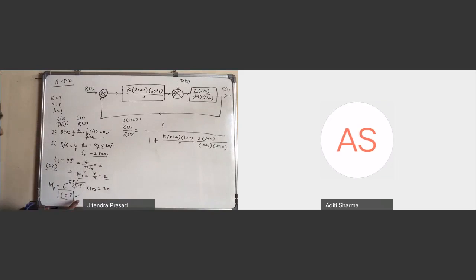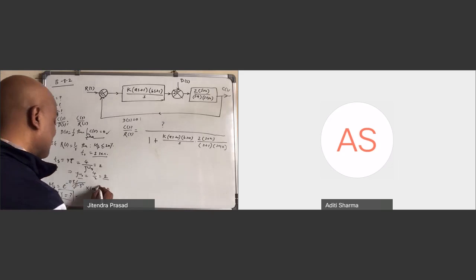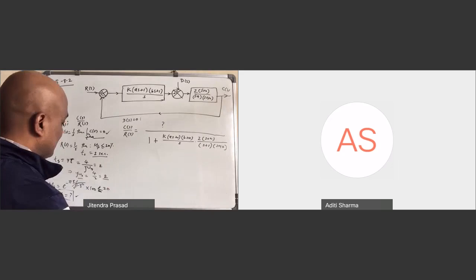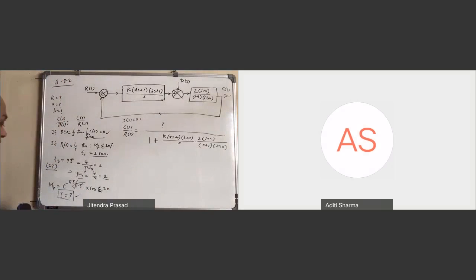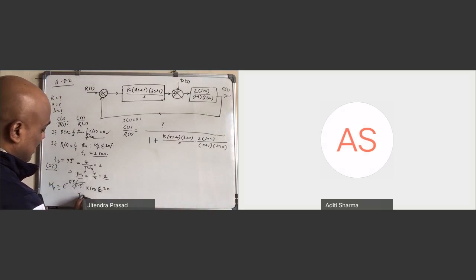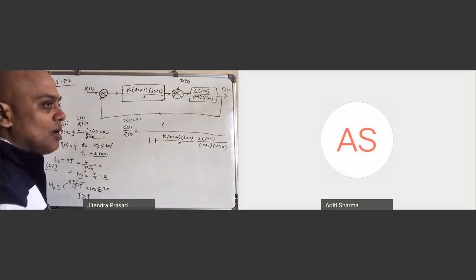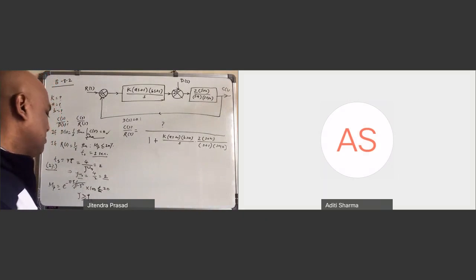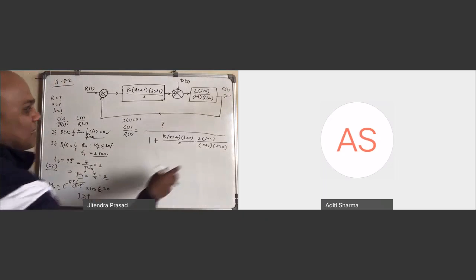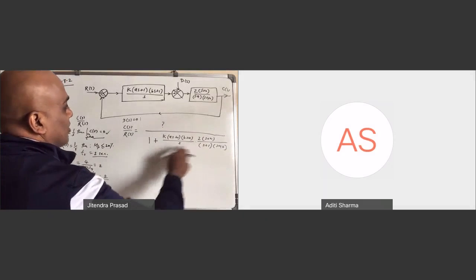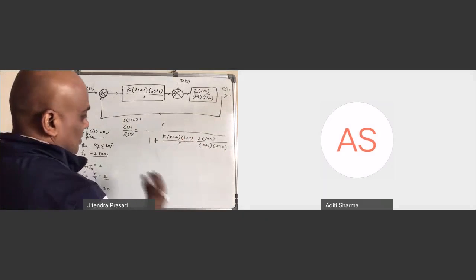Okay, and now if zeta is known, it says this or less. Remember, so or less. That means zeta should be greater than some value. It will tell you simply zeta has to be greater than zeta naught, where zeta naught corresponds to 20%. Okay, now you can design by any method. You can look at a root locus, for example. Root locus exactly tells you how things change when you vary k. So root locus is the best way to design it.